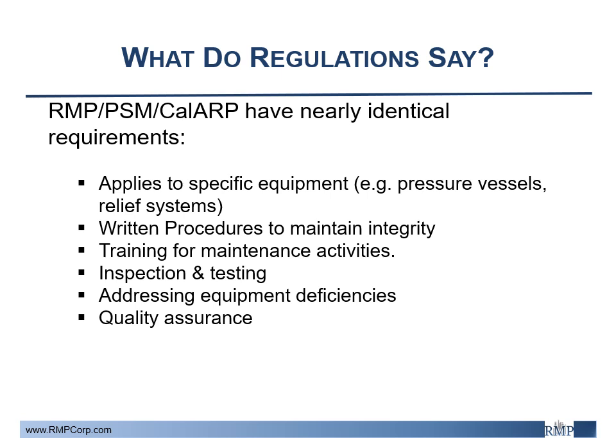From regulation, we see that the role of having mechanical integrity in the program is consistency and continuity. We may start with a perfect plan, but wear and tear does happen. Nothing stays perfect forever. So instead of waiting for something to fail or keeping a loose eye on our systems, we're actively challenging the integrity using a steady timeline of tests and inspections, documenting any findings, and ideally tracking any irregularities before they become issues and increase potential to cause someone harm.